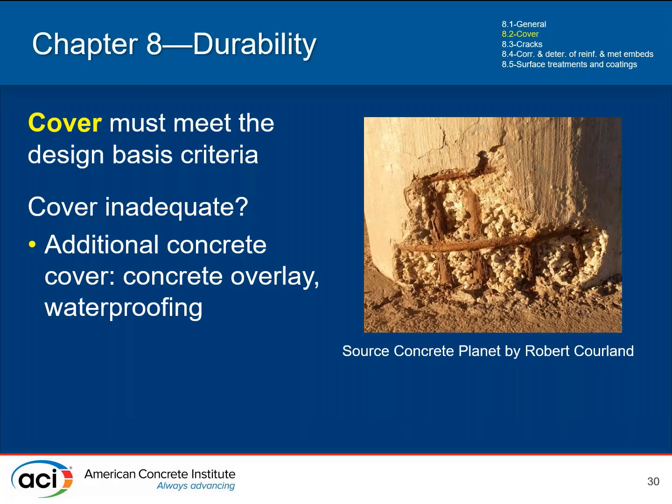If you're working on a parking deck or a bridge deck and all the cover's really low, if you have the structural capacity, go ahead and put down an overlay, get another inch or two overlay, something that you can do so that when you build it back, we have the cover that we needed, it's going to last and behave the way we wanted to, and we're not going to have trouble in another 2 or 3 years.